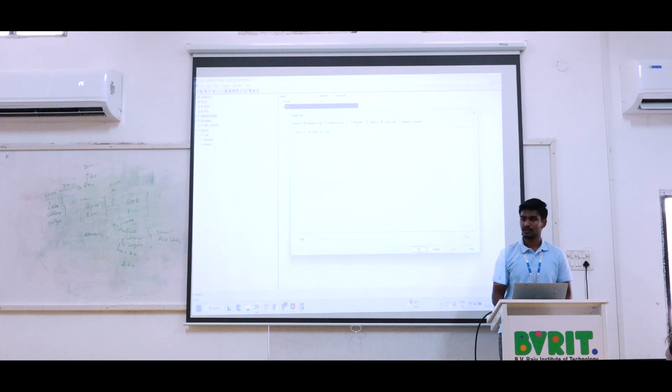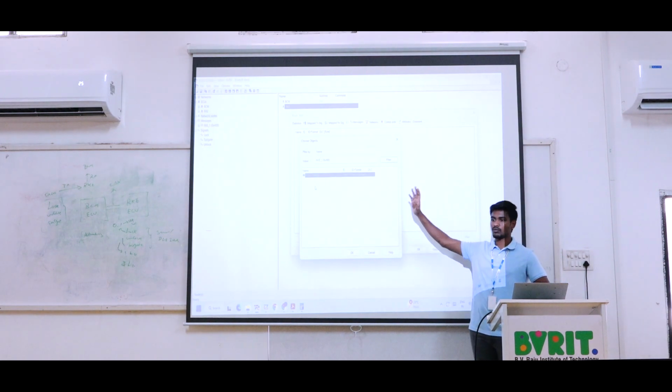Now we have selected the TX messages for transmission. We are not individually selecting the signal here. So go to select the messages, transmit the messages. Give the TX messages, click add. Then the messages you have created in the message column appear. As of now we have created only one message.